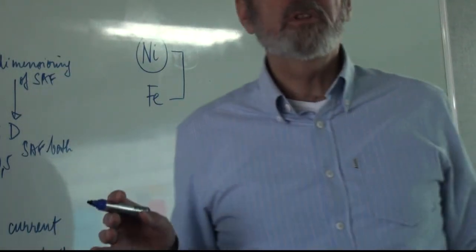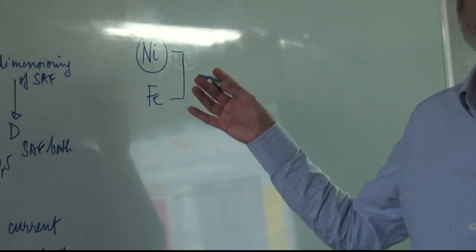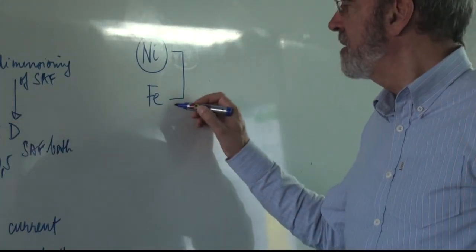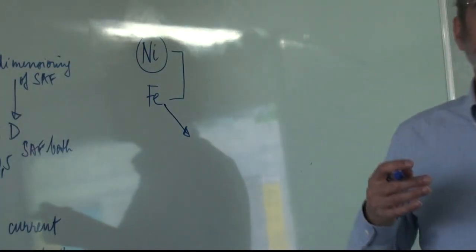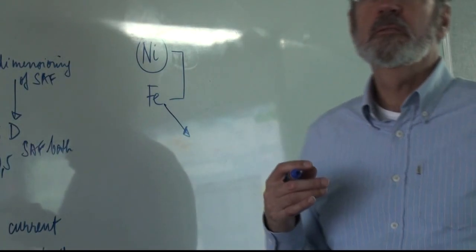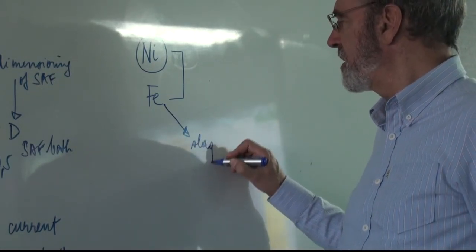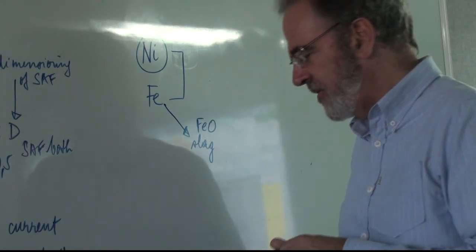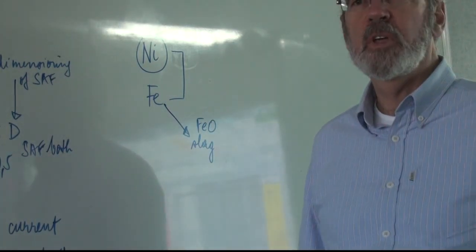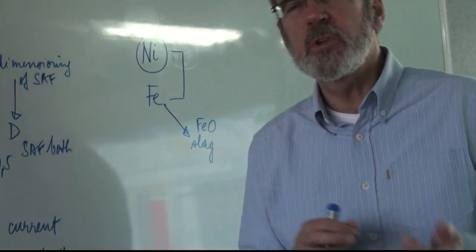But if you have too much iron in proportion, because it's a poor ore, then you will charge less carbon, and so you will leave some iron in the form of FeO in the slag. But nickel will be practically fully reduced.